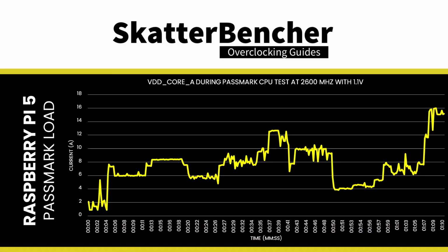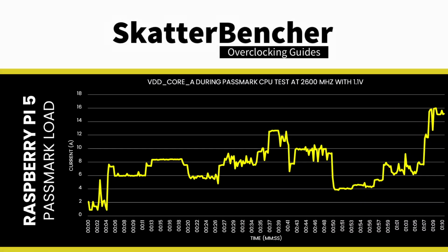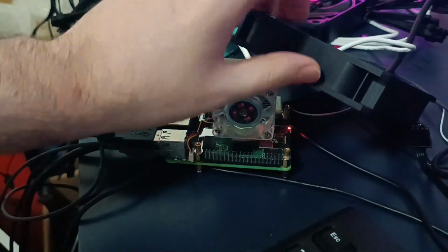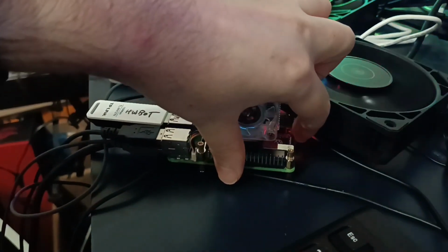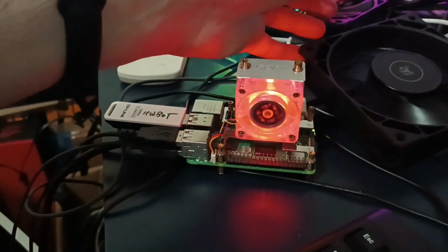If we track the current voltage and power of the VDD core during the workload, we find that the neon subtest is significantly more power intensive than any other subtest. When the benchmark crashes, the Raspberry Pi 5 completely shuts down. We have to manually press the power button to get it back up to working again. And also, during that shutdown period, we can't even communicate with the PMIC to see what's going on. The I2C bus is simply unavailable.